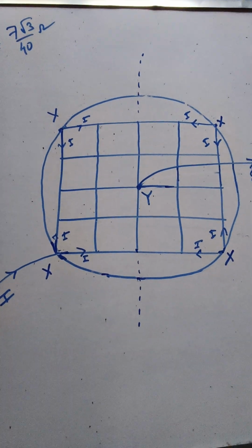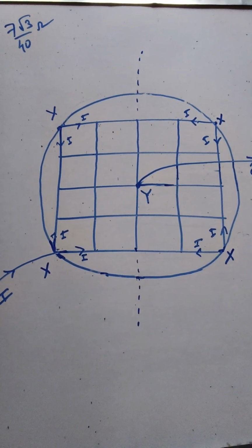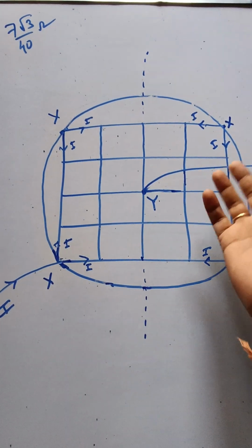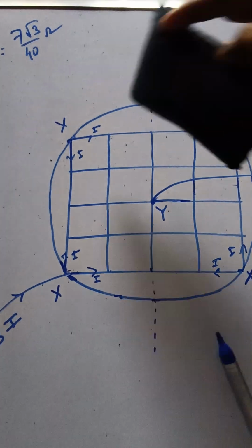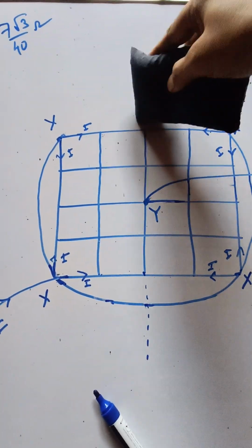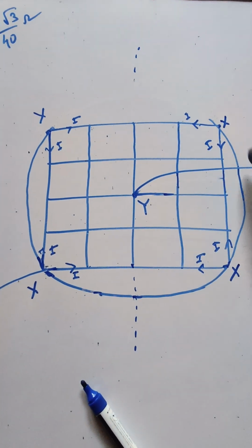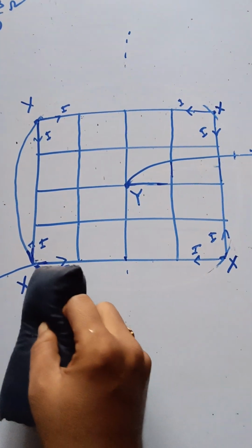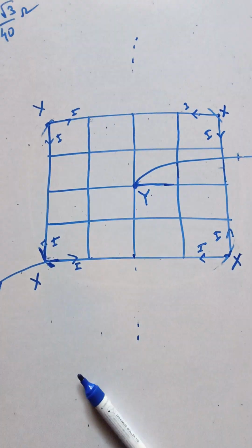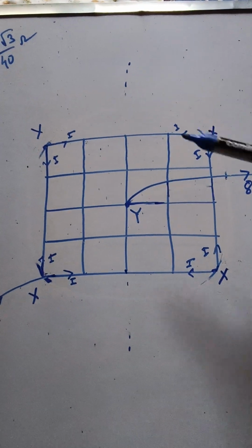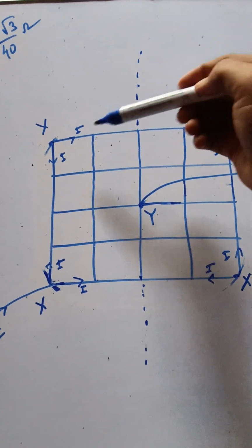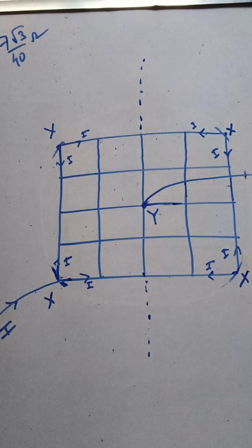You can join the points which have the same potential. So fold the circuit, and you don't need this wire now. You can remove this because it has no resistance. Now fold the circuit. All the resistances in that part will become half.